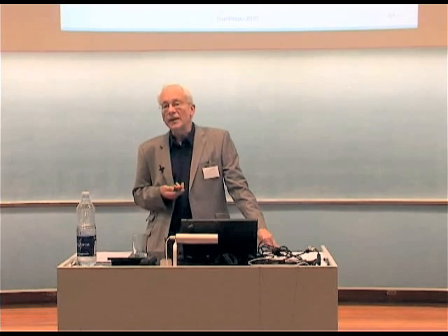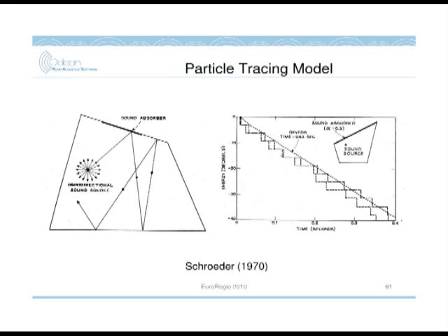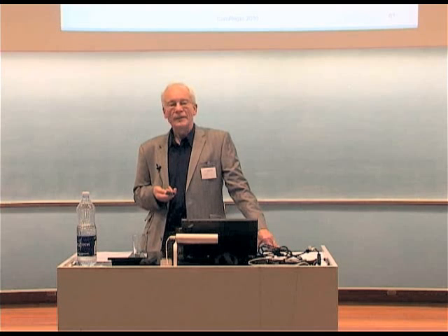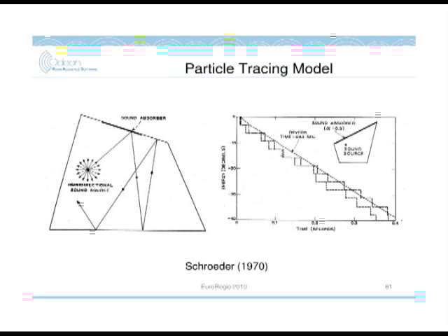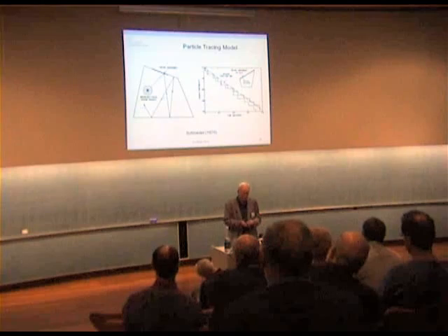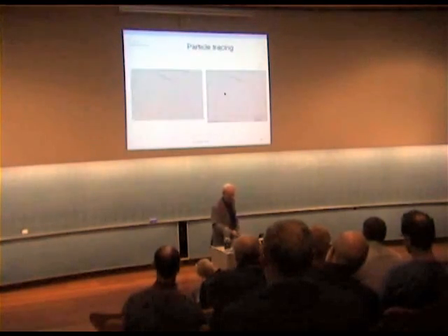So this principle is a very big advantage over the Eyring and the Sabine equations, where you actually have assumed the same absorption for all surfaces. And normally the interesting cases are when you have very unequal absorption, for instance a classroom in a school with absorbing ceiling and reflecting walls. But this kind of particle model will compensate for this and give you a decay curve, and from the decay curve you can then estimate reverberation time exactly as you do from a measurement.